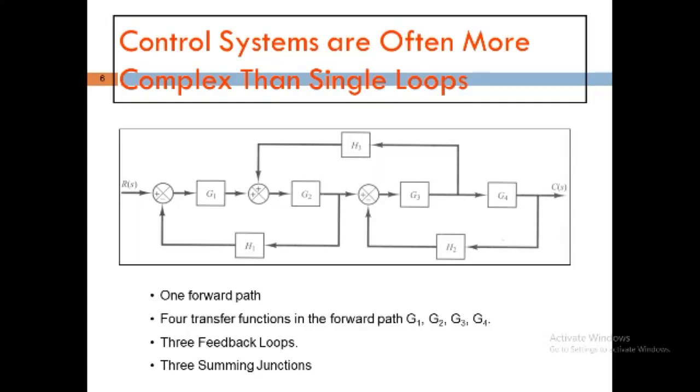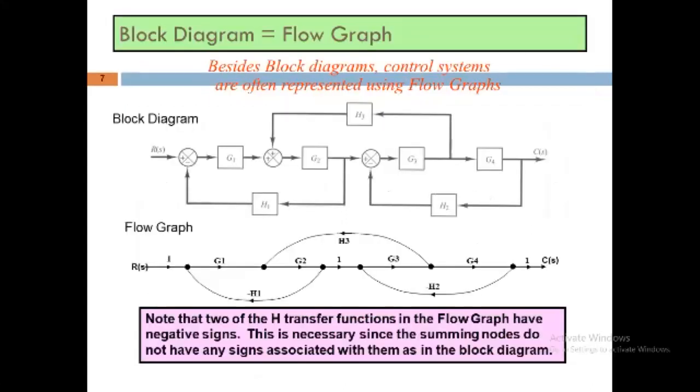Basically, for these signals and systems, if we want to learn about LTI, that is linear time invariant systems, for this purpose let us simplify that we shall deal only with systems that are linear time invariant. Now we are moving towards the definition of the transfer function. Basically, this transfer function gives us the relationship between the input and output, and hence it describes the complete control system.